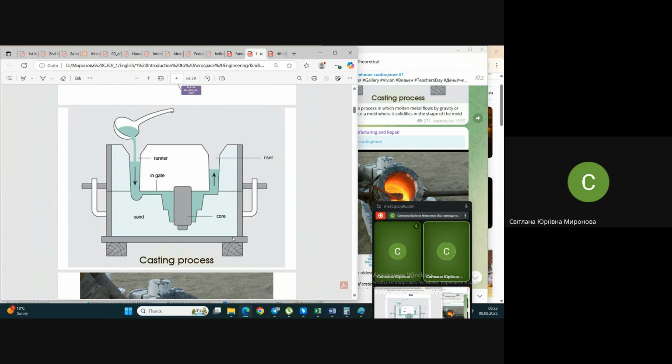You may compress it, you may make a shape, but it's also necessary to repeat somehow the shape of holes, and to repeat the shape of holes clearly. Usually in this mold, a so-called core is inserted, something that repeats the whole shape, and this something is made already not of sand, of course, quite clear.